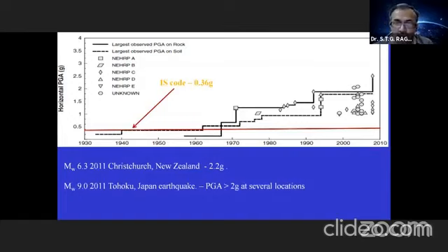As I already told you, when you are designing a structure, you want the structure to be safe in the future. Now, we have plotted this graph up to 2009. This record is being held, and right now no earthquake has exceeded it to date. So if we look at the next 50 years, like 2070 or so, whether the maximum PGA observed in the field will be 2.2G or whether it will be exceeded is a very, very difficult question to answer.